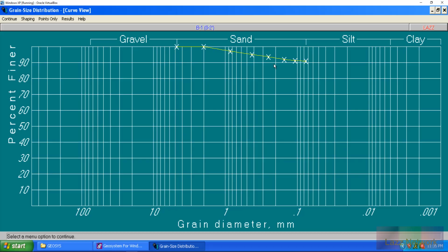I had an initial sample size of 363 grams that I split 100 grams of into my air quote hydrometer sample that was washed instead of a hydrometer performed. The only other steps that you would do if it's a hydrometer is you would let it sit in a solution of sodium hexametaphosphate.